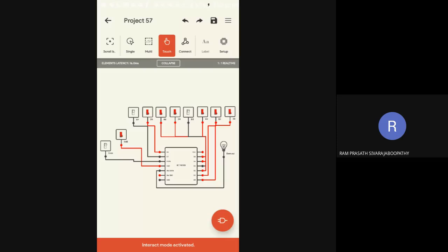Yes. So now parity checker. There is nothing much in a parity checker. For the 8-bit data I have given, it just shows what parity it is. Say for example, how many ones are there? 6 ones. We are talking about even parity here. So for the even parity checker, when the parity matches correctly, the output becomes 1. See what happens if it is odd parity. 5 ones are there. So what did the output become? 0. Okay, if it is checked, the output 1 means the given input is even parity. So we can check whether it is even parity or not using this.